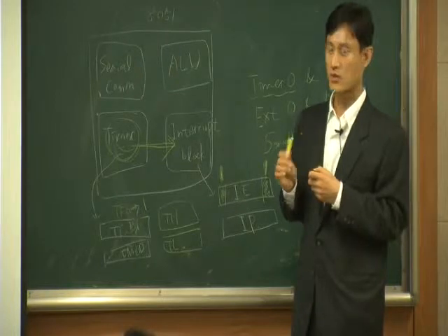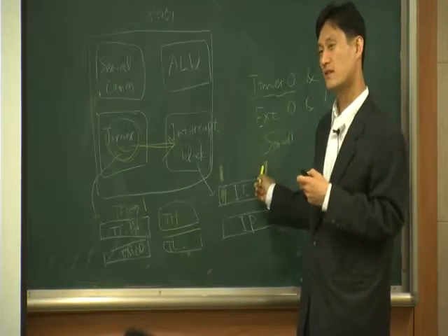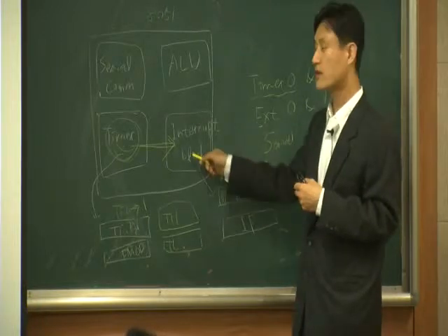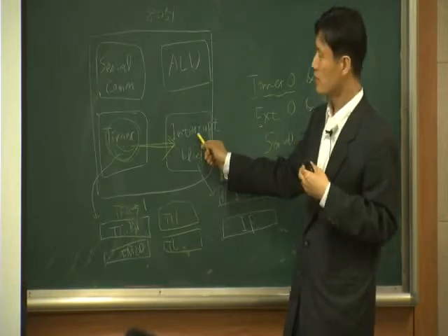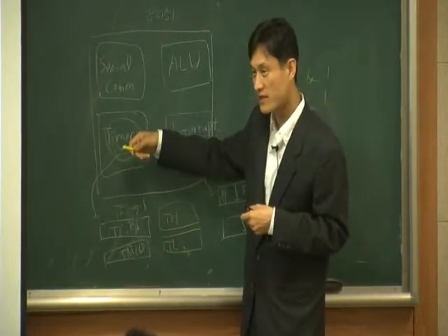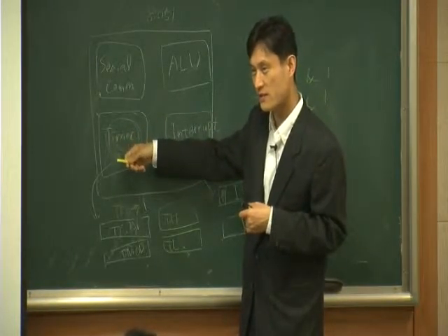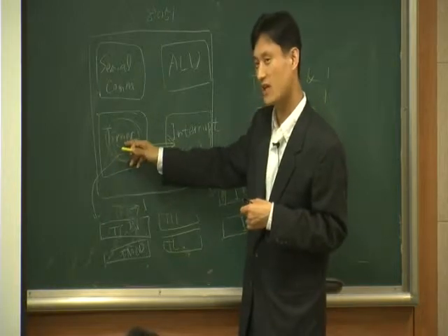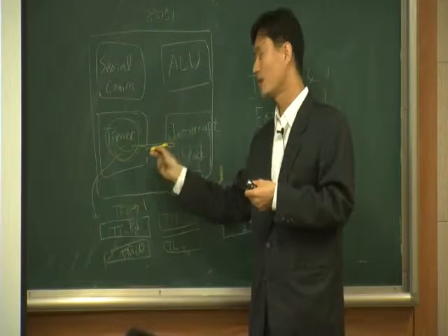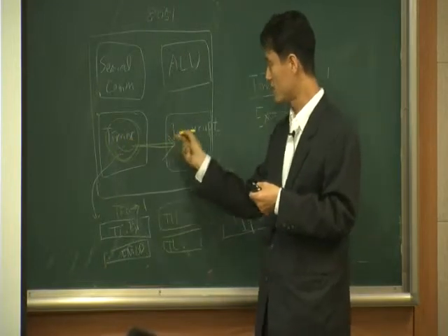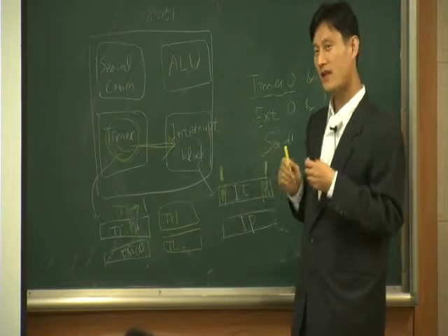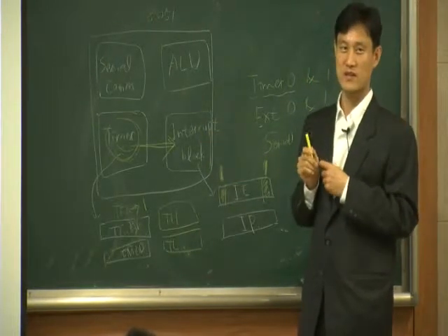Okay? So we need to have these 3 events. You have to set this one in order to get ready to get an interrupt. You also have to program the timer hardware such that the timer runs, and when overflow happens here in the timer, it actually gets an interrupt event. And when you have this event and you enable the interrupt block, then you get an interrupt. Software gets an interrupt.